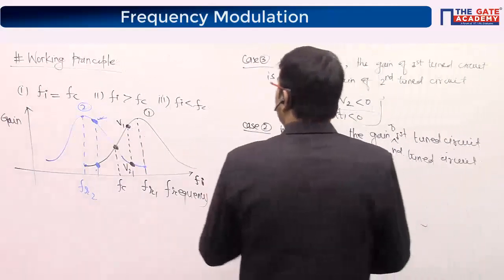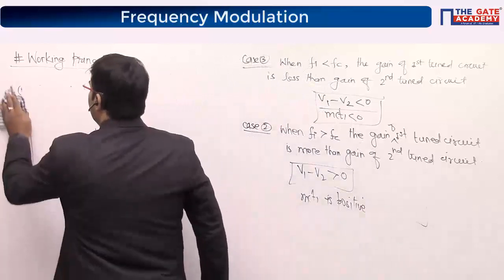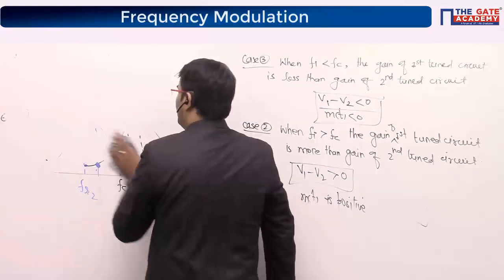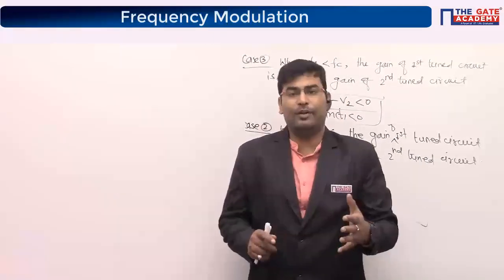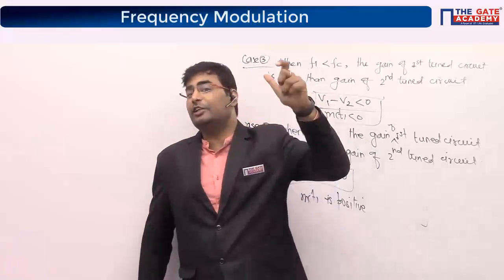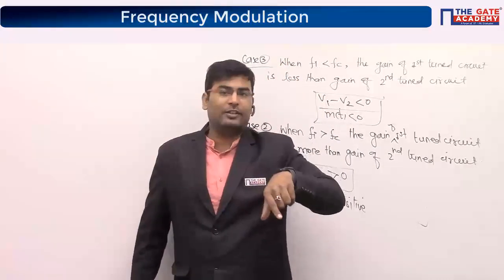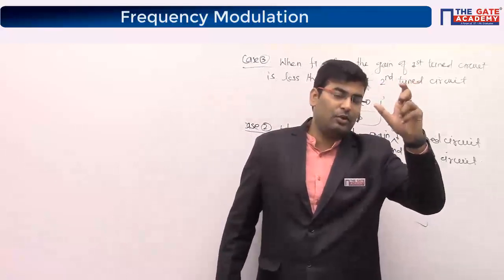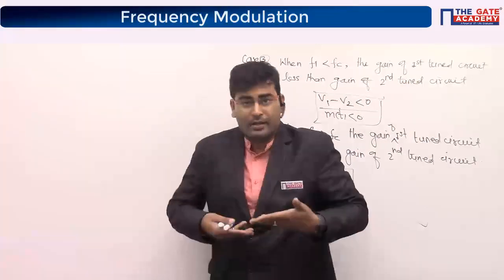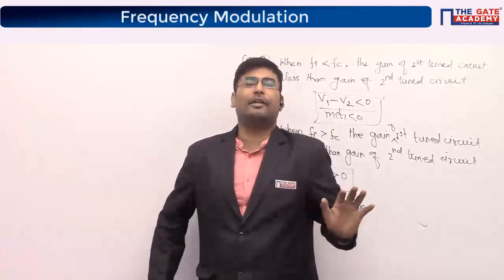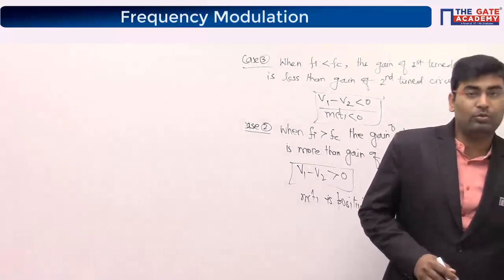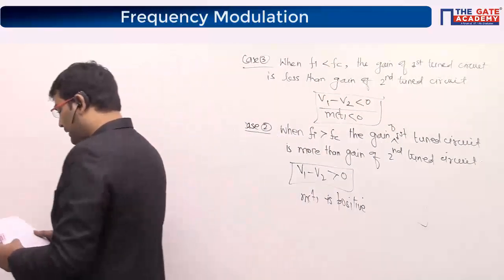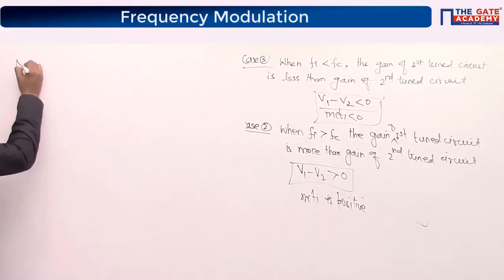Okay. So you can write that statement, guys. So guys, why do we call it as balanced slope detector? It's simple. Because one is giving you V1 and the other is giving you minus V2. So if I say V1 is positive slope, the output because of the second part, the bottom part, is just negative and equal. And that's how it is known as balanced slope detector. It has two components, both having equal and opposite slope. So write that as a note. If somebody asks you, you should be able to answer this.